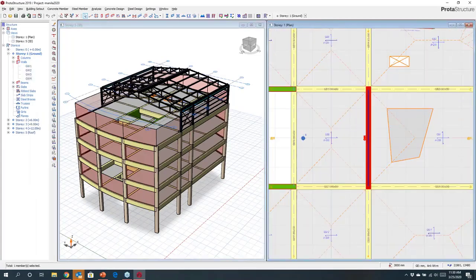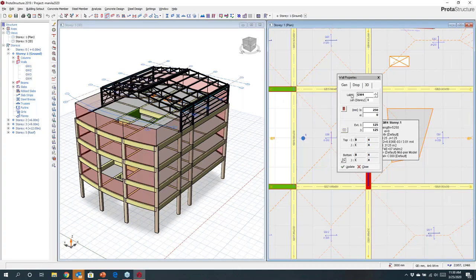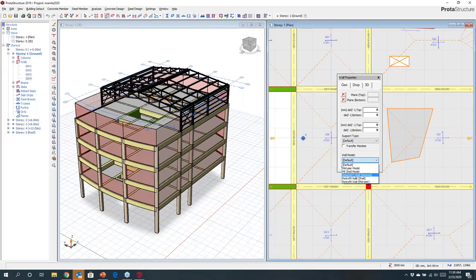If you are selecting, say, a wall, now we have different types of walls within the program. So it's not just general shear walls. We also have what we call basement walls. If you're defining a basement wall, it will be automatically meshed. And once we create a basement wall, we then know that we would proceed to look at doing a two-stage analysis for seismic.